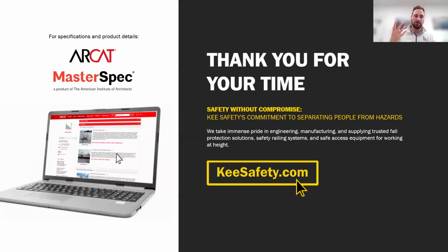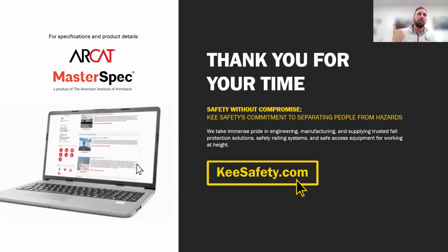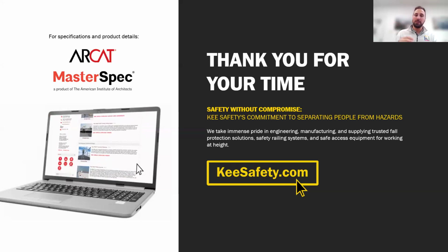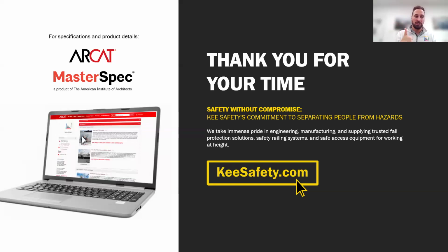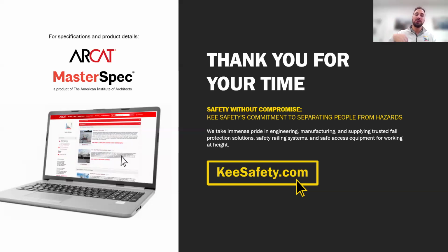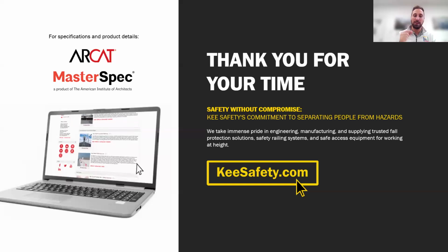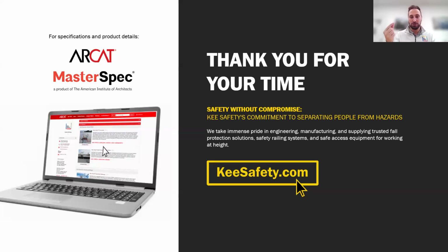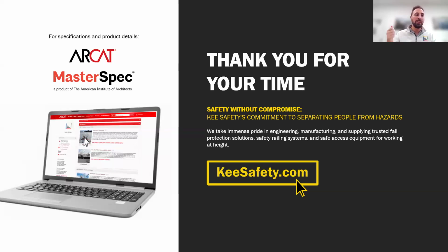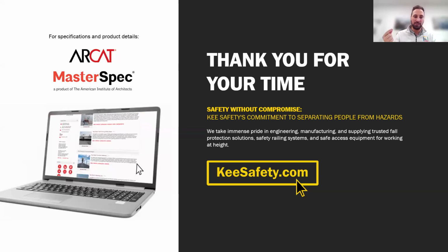But here's the nuance, or I guess my suggestion. When supplying an anchor point or horizontal lifeline, we work with trained integrators. They typically install nothing but fall protection. They have PEs on staff that meet the competent person requirements to design fall protection equipment. They're trained on installing and recertifying your equipment. They do the annual inspection, which is required by every single manufacturer of a lifeline system.